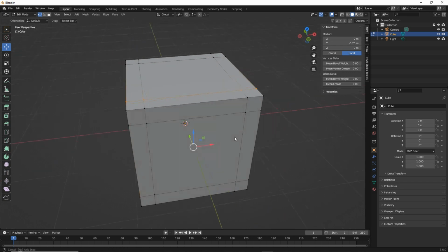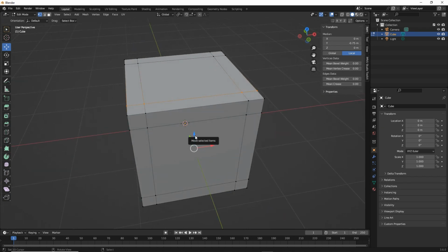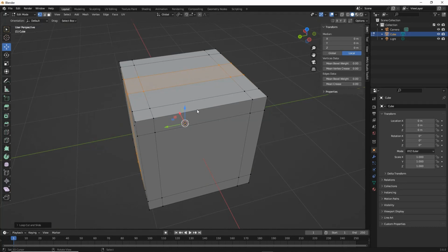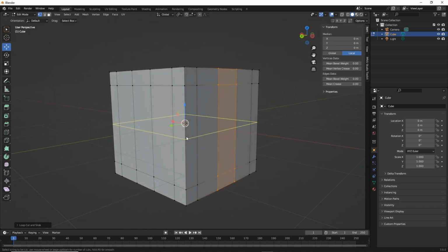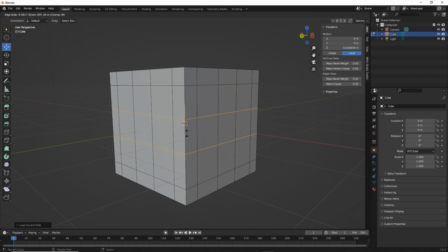And we're going to do the same thing to all sides, or the same thing will happen to all sides because of the loop cuts that we're now going to place. So again, I'm going to use the shortcut key, Control R, mouse up, increase the number of cuts. We want 2. Click to set, and then escape to confirm. So Control R, mouse up, click, escape to confirm. Control R, so we're selecting the orientation by mousing over this vertical edge, which orientates the tool horizontally. So mouse up, click, escape to confirm.